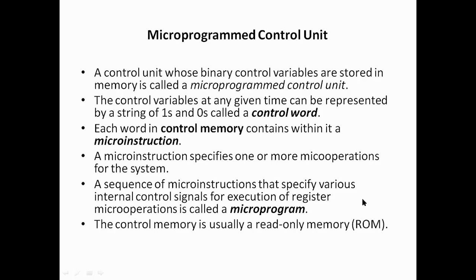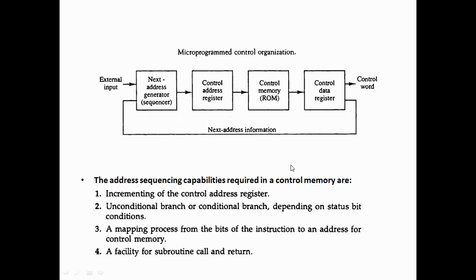And this control memory is usually a ROM, read-only memory, fine, because they are kept there in a read-only mode, and then the job is only to produce control signals. And here we can see a microprogrammed control organization. How does it work?